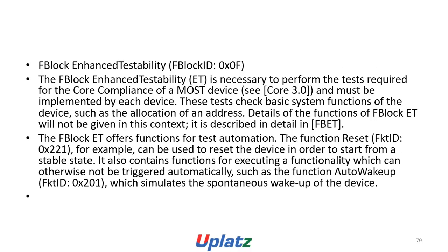FBlock Enhanced Testability, FBlock 0x0F. The FBlock Enhanced Testability, ET, is necessary to perform the tests required for the core compliance of the MOST device, Core 3.0, and must be implemented by each device. These tests check basic system functions of the device, such as the allocation of an address. The details of the functions of the FBlock ET will not be given in this context. It is described in detail in the FBET.